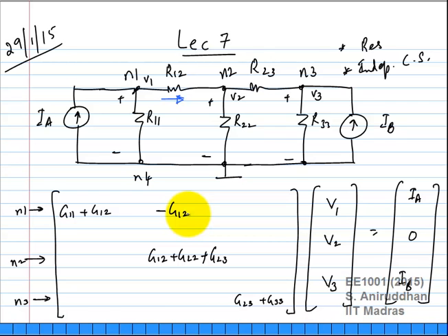Okay, what about the third column in row 1? That should depend on the conductance connecting node 1 and node 3. In this simple circuit we have taken, there is nothing connecting those, so this should be 0. Okay, and as we saw, the conductance matrix is also going to be symmetric, okay, because of the way we write the KCL equations. So you will have minus G12 here, you will have 0 here. Okay, what else? What about row 2 column 3? That would be minus G23.